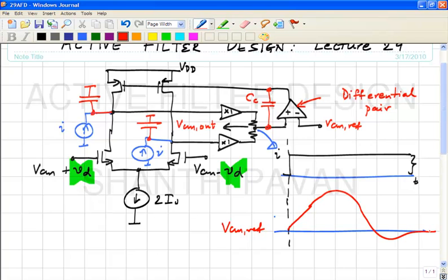Okay, this is just some example waveform I have drawn here. All that we are sure of is this ramp here. The slope of that ramp is very clean. It can be determined without any ambiguity or any knowledge of the rest of the network. Why? It's simply, what is the rate at which the voltage rises? I by C. Okay. Now if the loop is very fast, what do you qualitatively think will happen to this waveform?